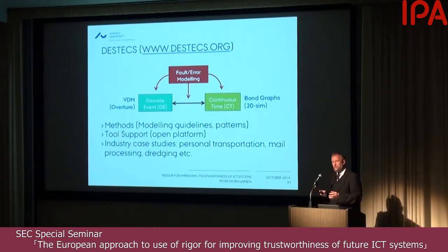What is important for control systems like these is that typically 80 or 90% of the software is actually not the low-level control, the PID control. It's the supervisory control. And that needs to take different faults into account. So what we are able to do here is inject faults in different places in order to model our controller such that it can be tolerant against such faults.